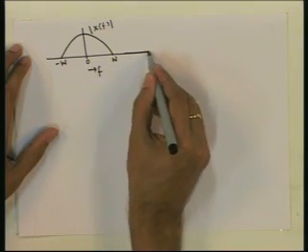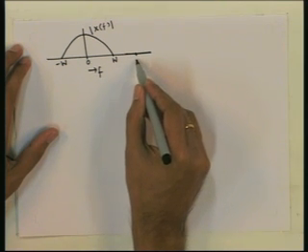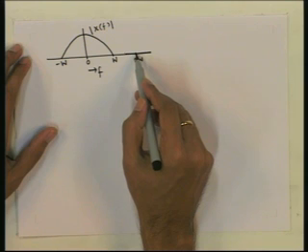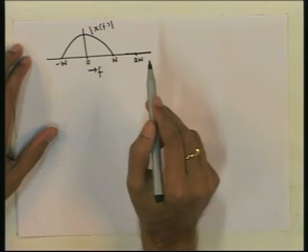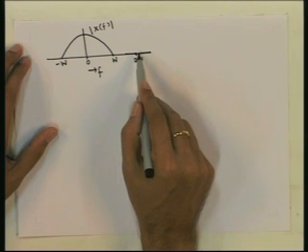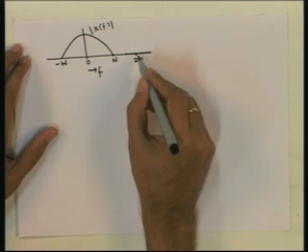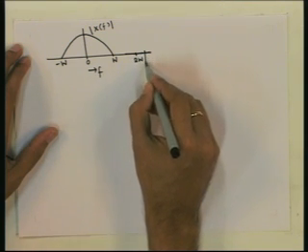Now, the Nyquist rate is 2 times this, that is somewhere here, this is Fs, this is 2 times W, but we can sample it either at a lower rate than 2W or higher rate than 2W. So, let us first see what happens if we sample the signal at a higher rate than 2W. So, this is 2W, but we sample it at, let us say, here.